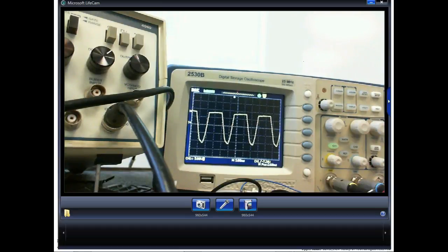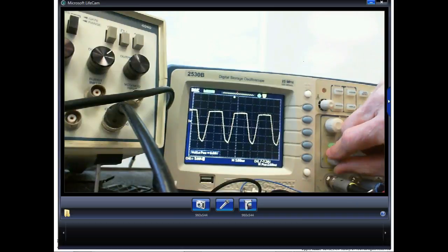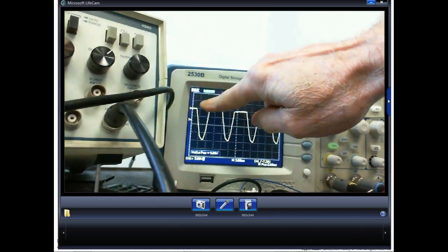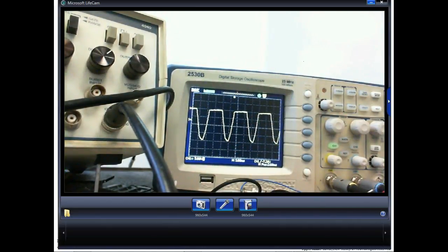Now, what are we going to use this for? This is half wave, and why do we call it half wave? Because we're only getting half of the sine wave. We call this half wave. Here's 0 volts up here, by the way, guys. Let's put it online. We should get the same thing negative that we got positive. The math is the same. The only thing you've got to do is understand the sign, right?